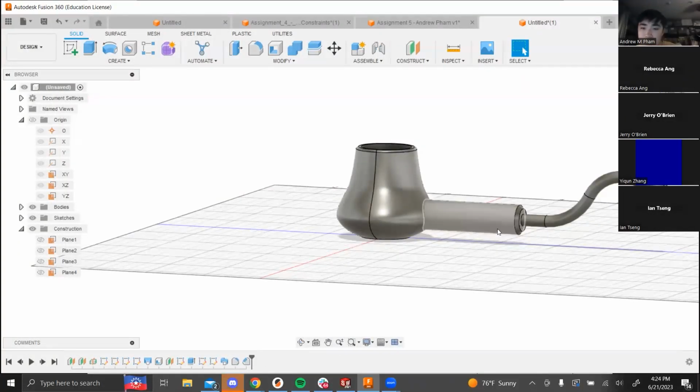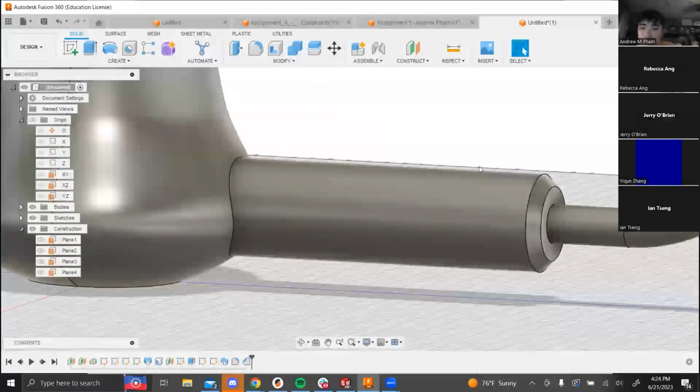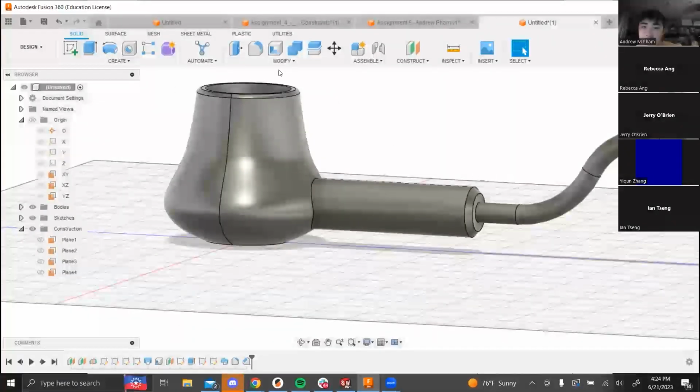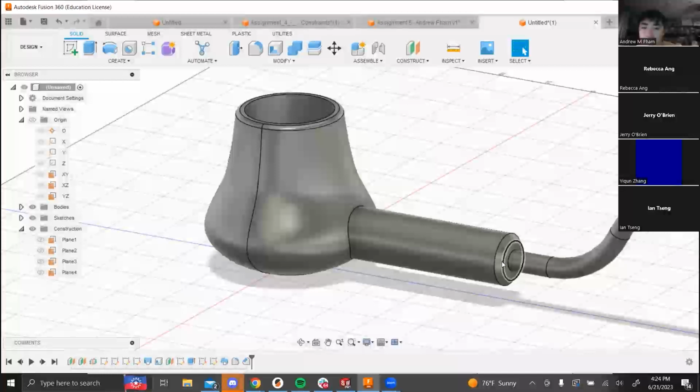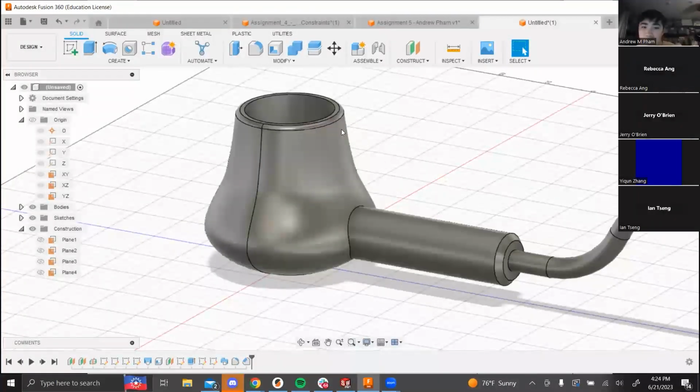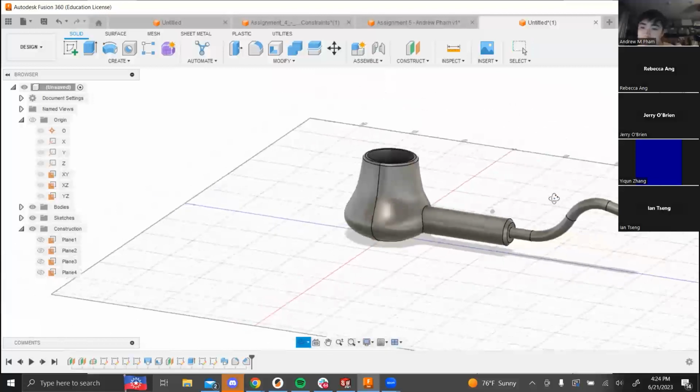There's less options and less complexity on the ends. So I like to put all of these, like the chamfers and the fillets, at the end, because it just kind of cleans up and dresses up your part. But it makes it a lot easier to edit if you have all your major operations and things like that beforehand, if that makes sense.